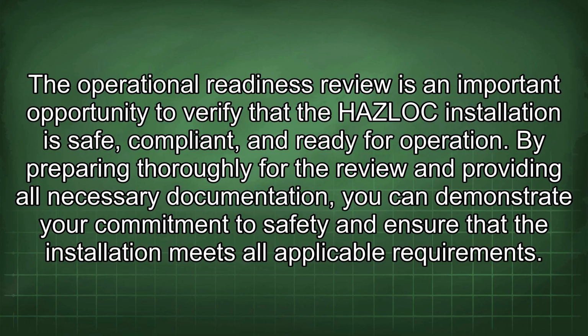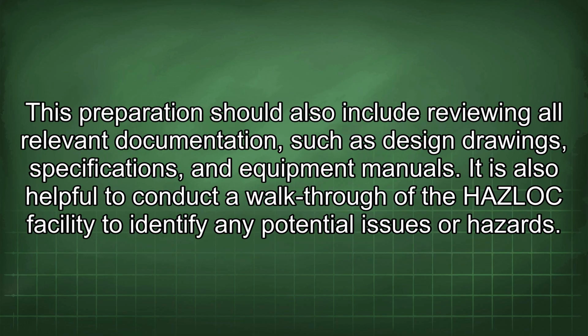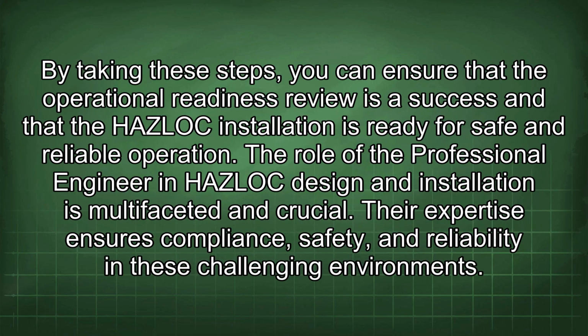operation. By preparing thoroughly for the review and providing all necessary documentation, you can demonstrate your commitment to safety and ensure that the installation meets all applicable requirements. This preparation should also include reviewing all relevant documentation such as design drawings, specifications, and equipment manuals. It is also helpful to conduct a walkthrough of the HAZLOC facility to identify any potential issues or hazards. By taking these steps, you can ensure that the operational readiness review is a success and that the HAZLOC installation is ready for safe and reliable operation.